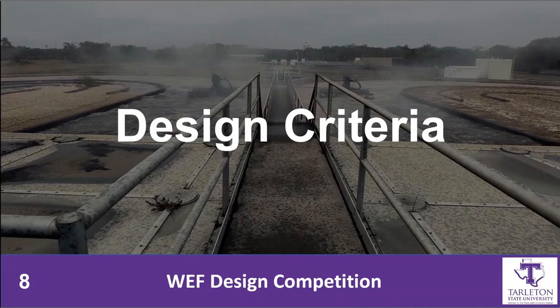There are 3 major factors when defining the design criteria. These are state-specific, such as influent wastewater characteristics, and TPDES discharge permit limitations or client requests. Many of the client requests have already been mentioned in the project scope. Some that have not been mentioned but were also considered were odor control due to the proximity of the site to a local park. Additionally, TCEQ requires standards to attain the Type 1 and 2 wastewater reuse currently practiced at the plant. Some more general considerations made in the design include the environmental impact, operational ease, and safety hazard minimization.